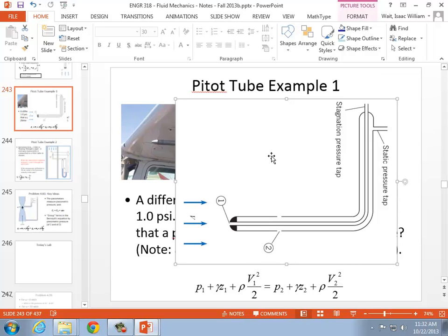And so since the air wants to go in but can't, there's a boosted pressure in that center part of the pitot tube. There isn't a boosted pressure in the casing around it. You can see that this static pressure tap is connected to the outside casing, and there isn't an increase in pressure because the streamlines just go right past it. The wind isn't being stopped by the opening as it is here in location 1.